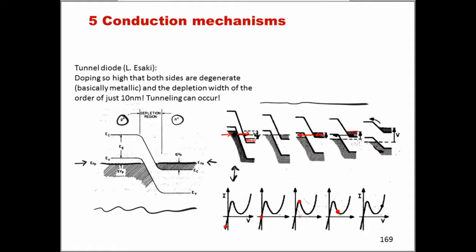If we keep increasing the voltage further, then effectively we prevent any other tunneling situation. The only thing that can happen is that some electrons acquire enough thermal energy to overcome the barrier existing in the PN junction due to the depletion region, and so we know how it goes. Then it becomes effectively a standard PN junction.